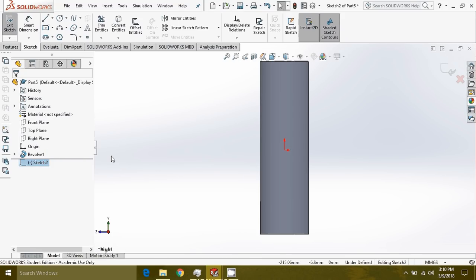Now that works for everything. If you were to say create a constraint between two parts in an assembly, you could do the same thing, right? You could create mate, then open up the tree and find those other parts. So that's always there. Your tree just shifts from here. As soon as the dialog box pops up, it shows up over here. You just have to expand it.